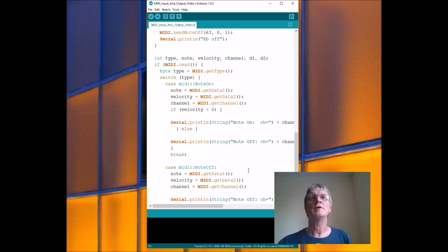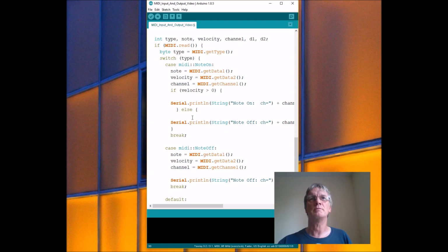And then when you get to the MIDI input routine, before each serial print line command where you print the data to the screen, you add in this extra line of code, which is pretty much the same thing, but this time instead of using the actual numbers, you use note, velocity and channel. So this is the usbMidi command.